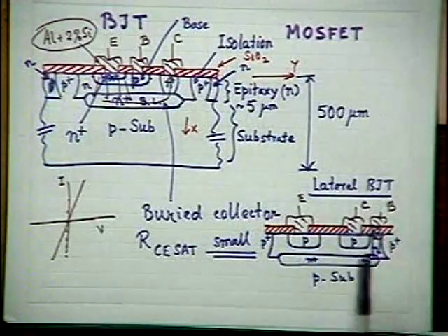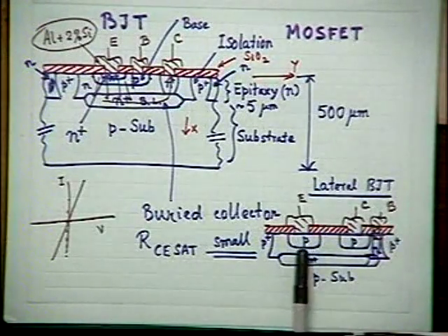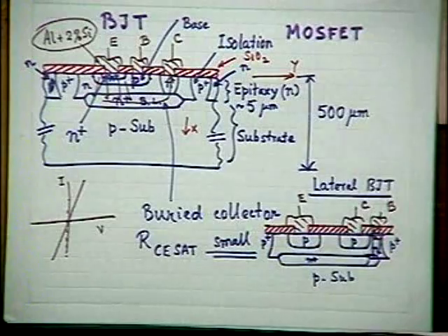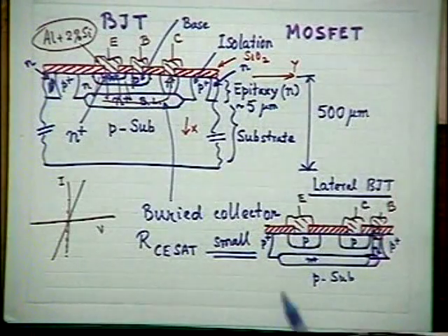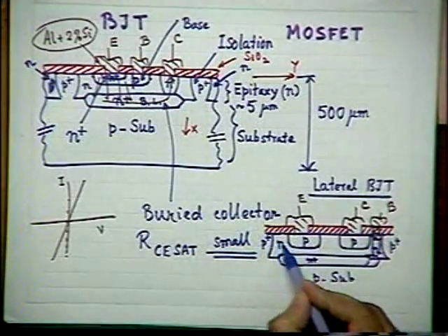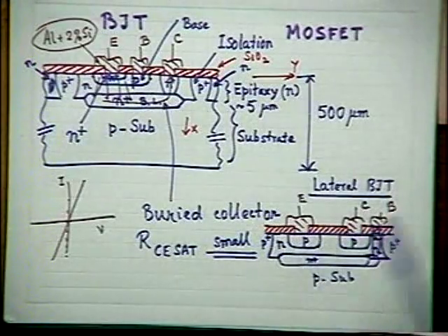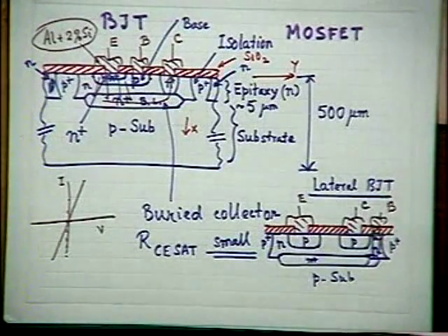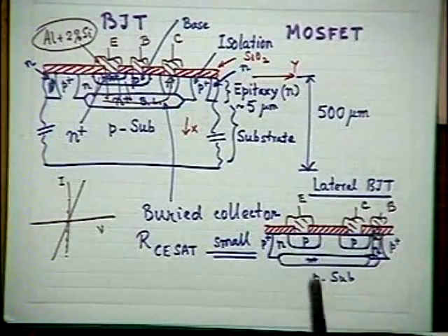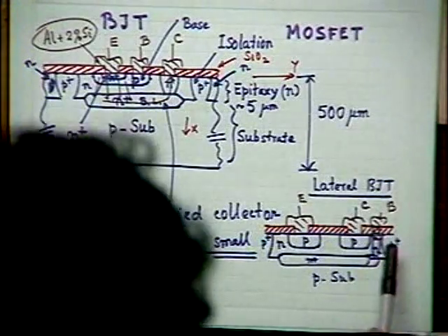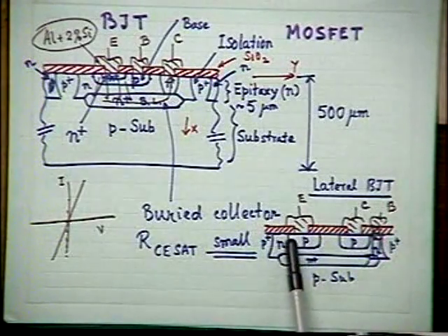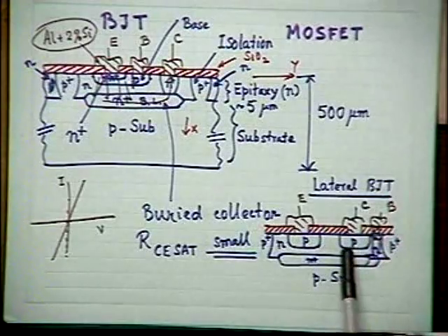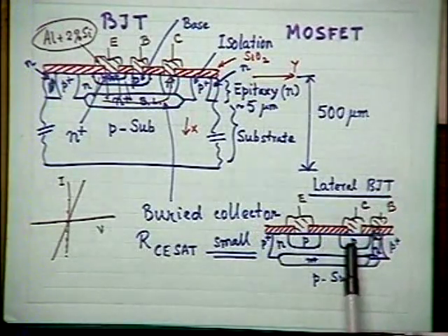You see what has been done here. This is an N-type region, the epi layer, which is one of the islands where a transistor or any component can be developed. And you see that there are two p-type diffusions or implanted regions. There is a detailed structure, but let us not go into that.